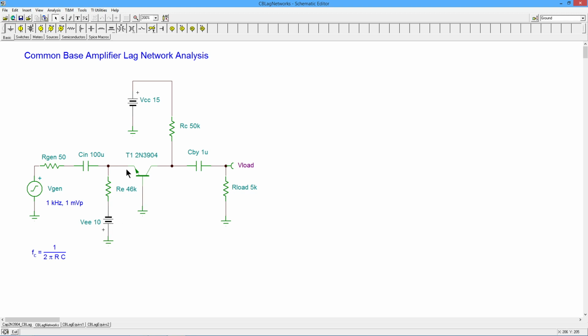If we look at a simplification of this, an equivalent circuit, we would take the coupling caps and short them. I mean, they're a short for mid-band, so they're going to be a short at anything higher. Power supplies, we short those, replace them with their ideal internal resistance, so that's a short. So we see RE going to ground here. We see RC, just mentally flip that down because that's ground. You want ground down here. So we'd have RC out here.